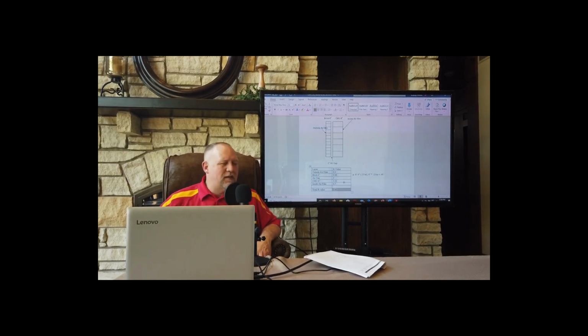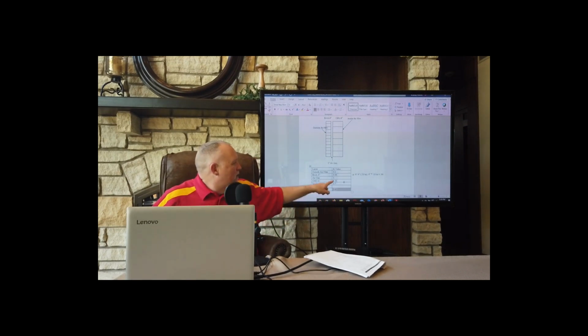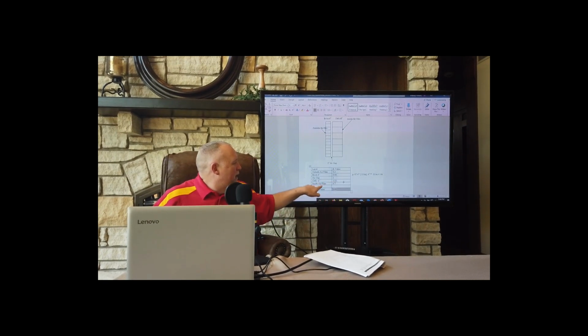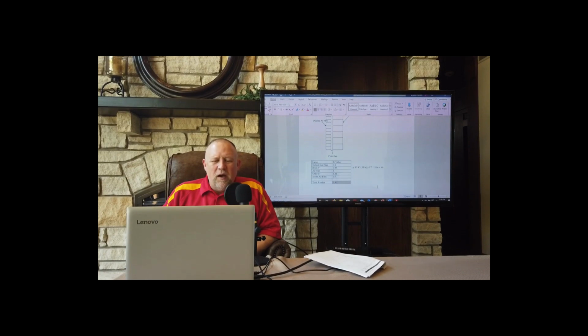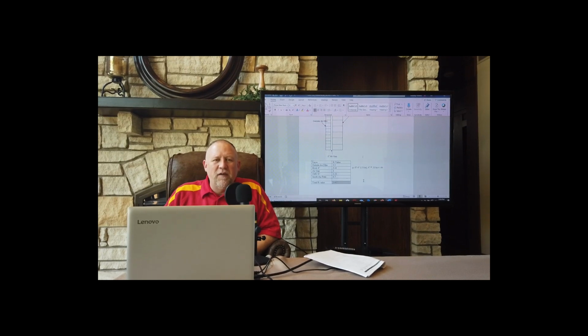masonry unit. Don't forget to use the sand and gravel aggregate concrete masonry unit. It has an R value of 1.11, and then the inside air film of 0.7. We add all those up, and we get an R value of exactly 3.45, which, in terms of the R value and energy performance of a wall, is not very good, to be honest. It's not.